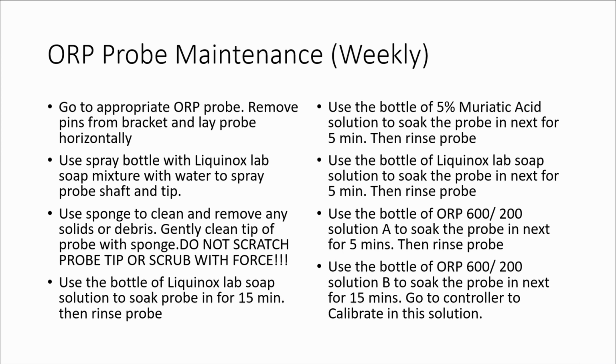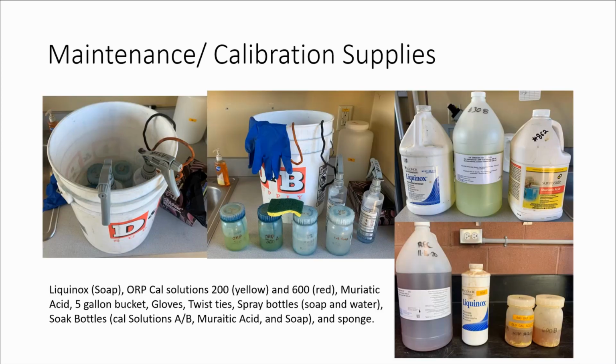So if it's your influent flow meter, a 2-point calibration is 0 and max, and then it'll span between it. Or a pH probe, you're usually using 3: 4, 7, and 10 pH. So again, is this single or double? Single. Just for everybody, single point calibration on this one. Okay. So if they get that answer wrong, they're not paying attention.